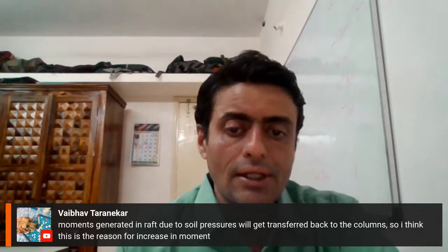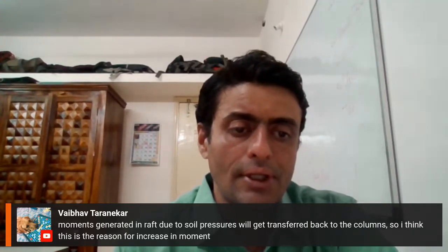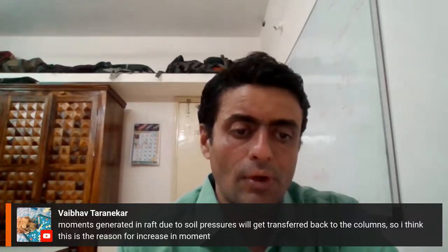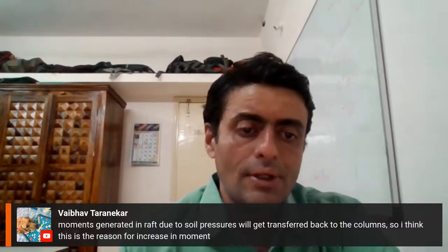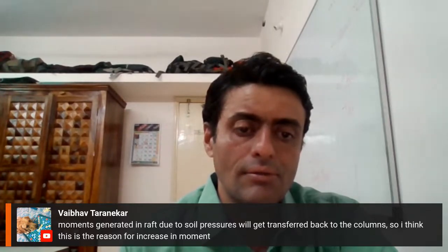Very interesting. I think he should present this in a better way. Perhaps we will call him in the next episode and he can share these findings in a more proper way with us. He is continuing that the moments generated in the raft due to soil pressure will get transferred back to the column. So I think this is the reason for the increasing moment.